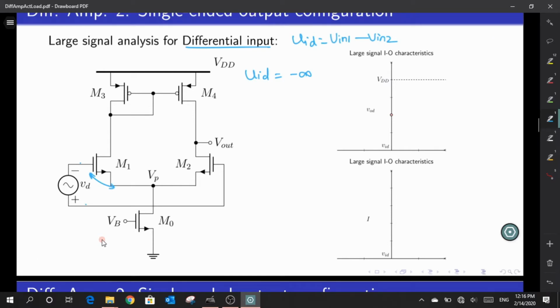Okay, so I think I'll just change this polarity here. I'll just make plus and minus here. Okay, so what happens is that because my Vin2 is much larger than the value of Vin1, I have a negative value whenever I have this kind of situation, which means that I'm talking about a most negative value. So in this case, my Vin1 doesn't have enough value across its VGS to make this M1 be on. So because of that, I will have this M1 under off condition.